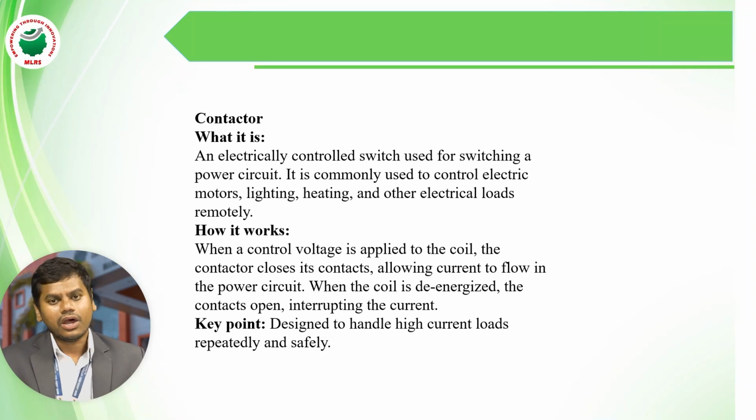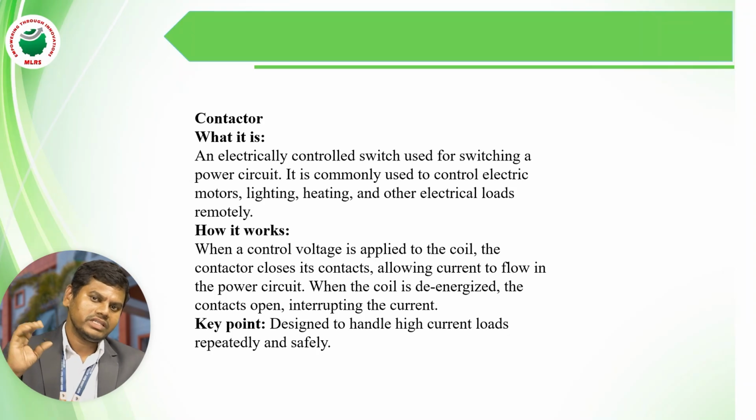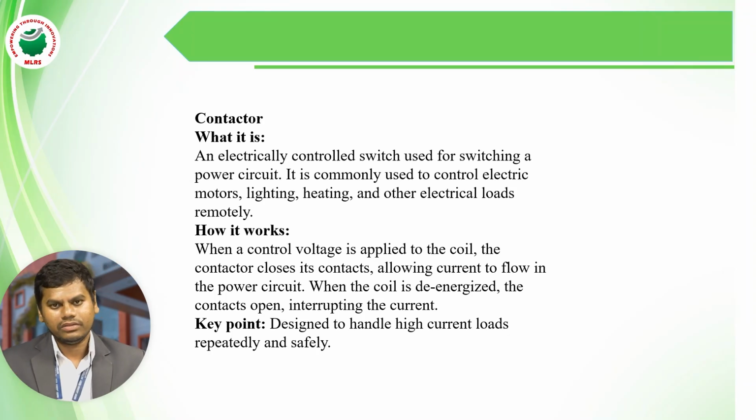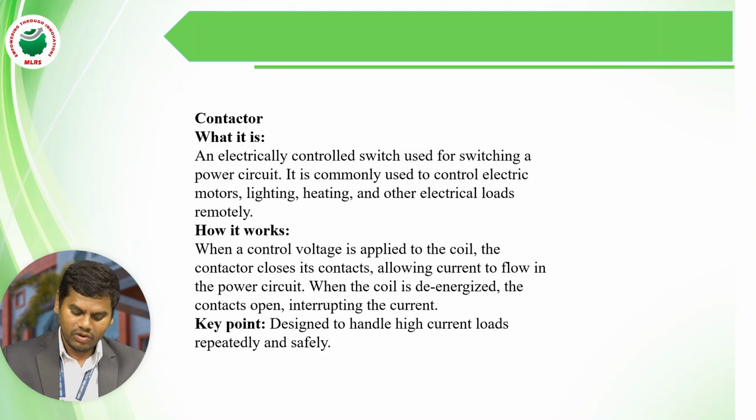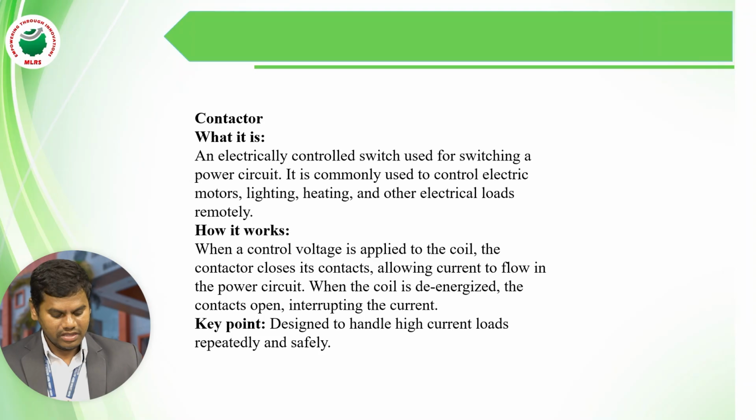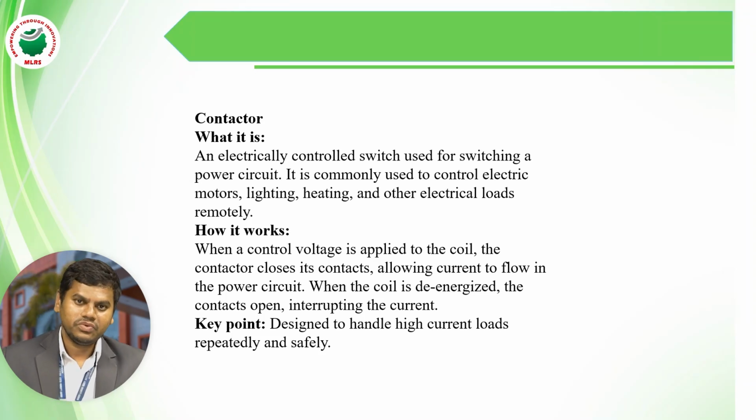Next, how does it work? Okay, we'll see how it works. When a control voltage is applied to the coil, the contactor closes its contacts, allowing current to flow in the power circuit. Then when the coil is de-energized, the contacts open, interrupting the current.